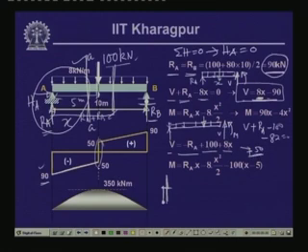On this side we had minus 50, and on this side of the loading we have plus 50. So, here we get the ordinate over here. Basically, if we enlarge this particular part, it will appear that we have a variation like this, but this distance being very small, we take this as a straight line. So, there is a jump of the shear force from minus 50 to plus 50 immediately after this load point.